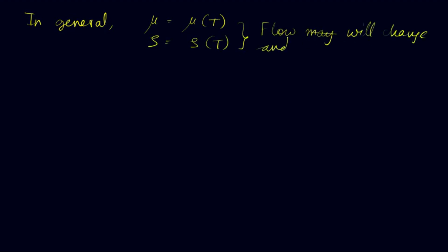In general, the flow will not be unidirectional. The reason being, there is a change in viscosity and density as the flow progresses in the tube. This is because the flow is continuously receiving heat through the walls. As the fluid heats up, the viscosity will reduce, so will the density.